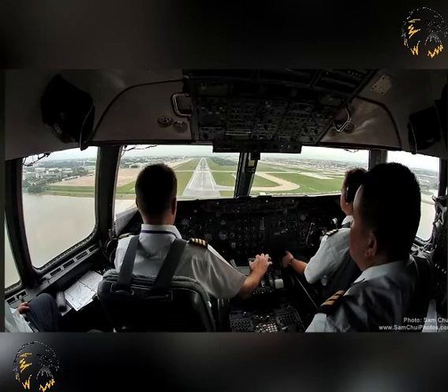The width of the ILS final approach area is much narrower than those of non-precision approaches, and descent must never be initiated until the aeroplane is within the tracking tolerance of the ILS localizer. The ILS Obstacle Assessment Surface, OAS, assumes that the pilot does not normally deviate from the centerline by more than half-scale needle deflection after becoming established on track.